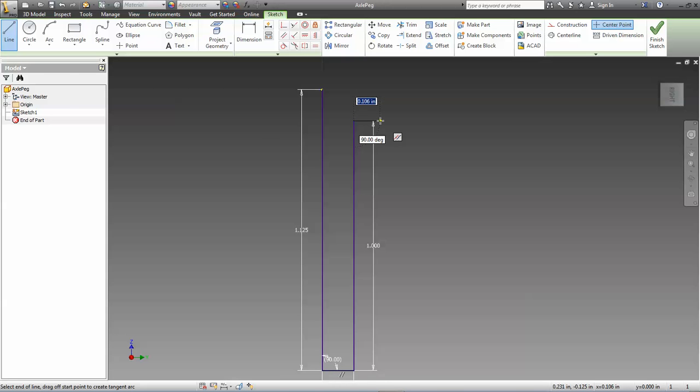Then the overhang here, you have to again do some more math. You'll see a note that the diameter of the head is 0.422, which means the radius would be 0.211. And we already know the radius of the shaft of the bolt is 0.125. So we can make the overhang 0.211 minus 0.125, which I believe is 0.086. Yes.